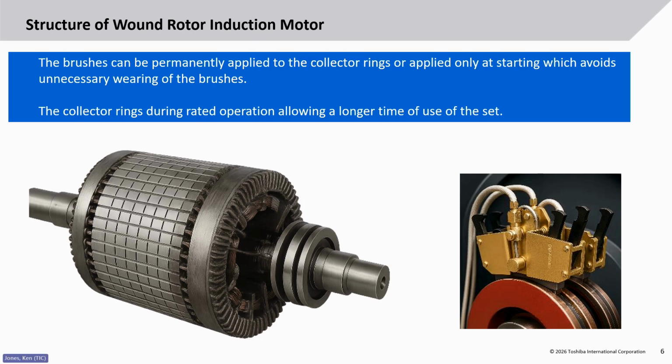Now we look at applications and say to ourselves, why would this be necessary? If you're not requiring special conditions for long periods of time, this design with a wound rotor machine can be very cost effective. Now it does require additional maintenance and additional equipment associated with it, but it's far less than using a variable frequency drive.